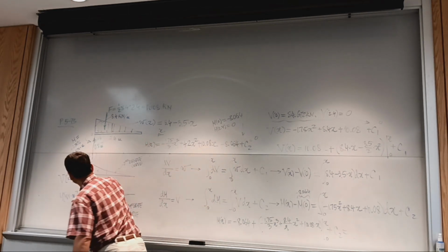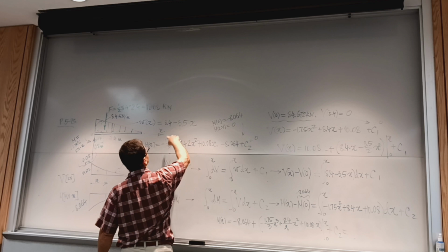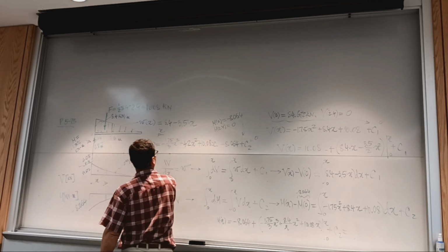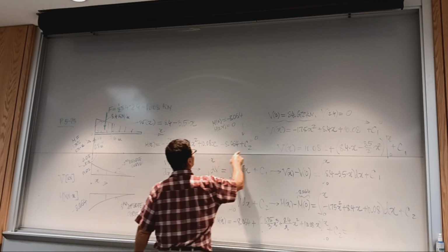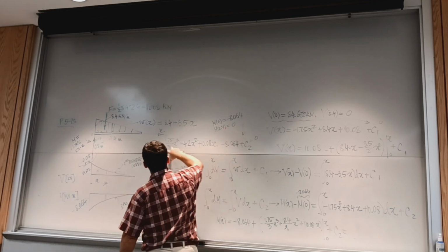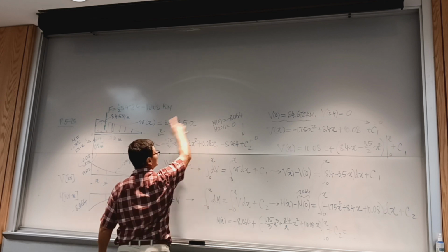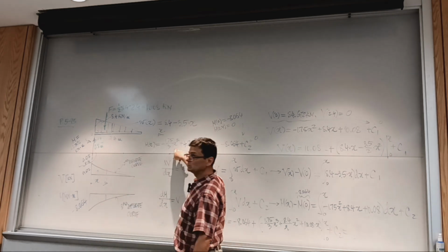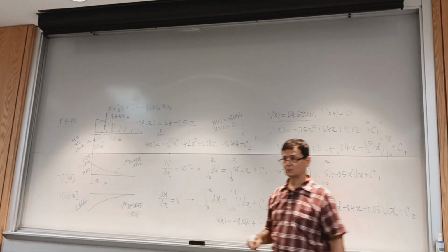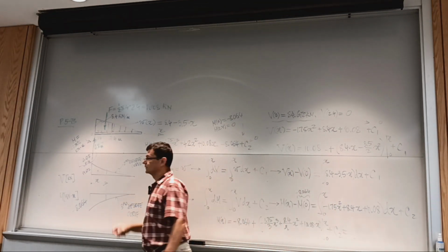Moment is this one. When you make x equals 2.4, that is the left or the right hand end of the beam, and from the first condition, this should go to 0. You should have everything equals 0. So if I make 2.4, it should go to 0, according to the diagram.